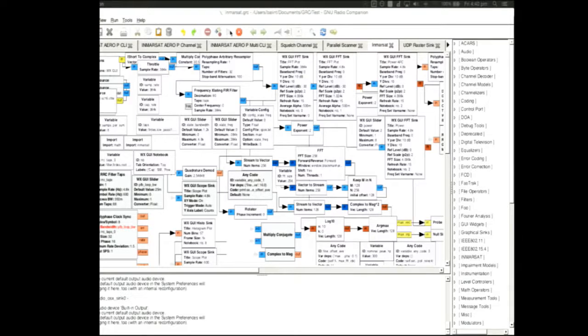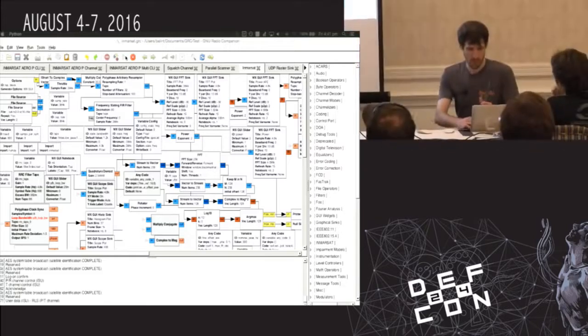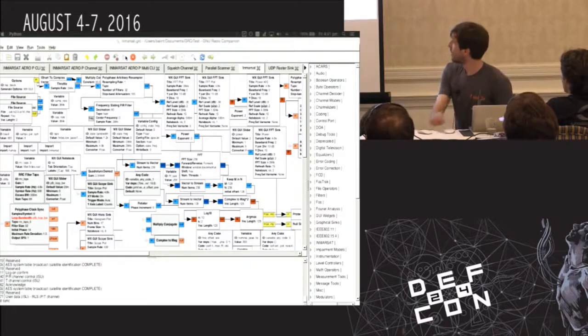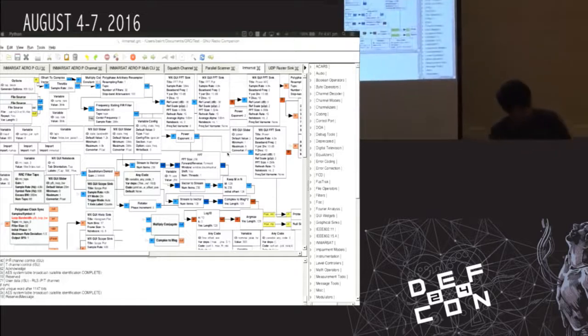So one other nice thing you can do, and I'll show you how this works, is that if you've got simple data streams like this, it can also be a bit of a clue to actually listen to them, because this is slow rate data and it's FSK. You can pretty simply modulate this into your sound card, and you get something that sounds like that. And that sounds like it should. So you can see down the bottom there as it's actually working.